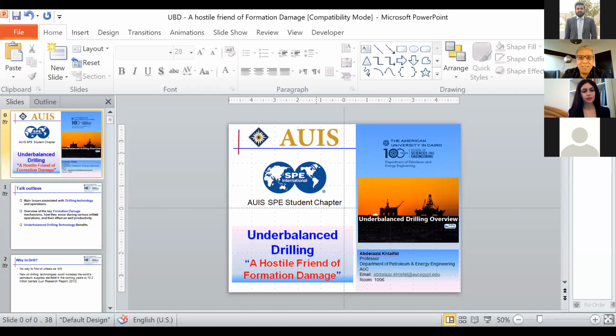And in this case, you cannot introduce large damage to the reservoir. And you still need to make an assessment or screening for such a depleted reservoir, whether it can really be drilled underbalanced or not. So you have to gather all the info and go through a candidate screening procedure. There are different software packages used for this.